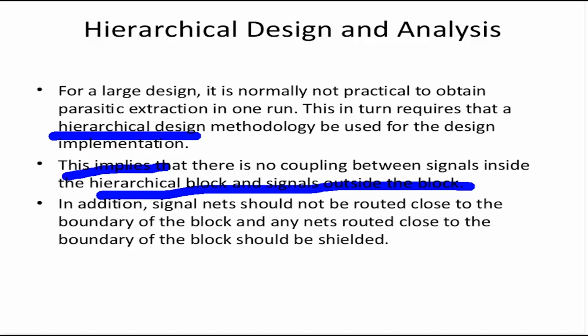But consider the memory controller now. It is a separate functional block, and it would also be a separate layout block. That is usually the case. So it would be synthesized separately. The functional timing would be closed at the block level also, plus all the noise and crosstalk data would be analyzed at the block level, at the memory controller level, and not at the chip level.